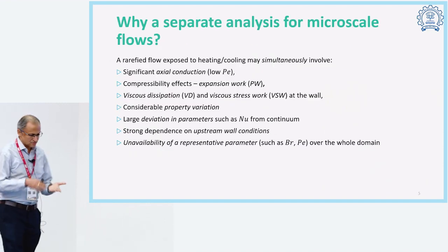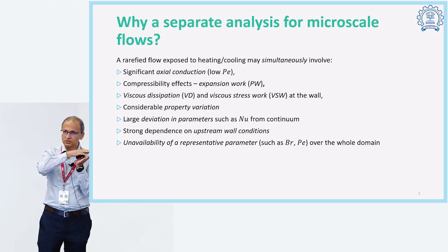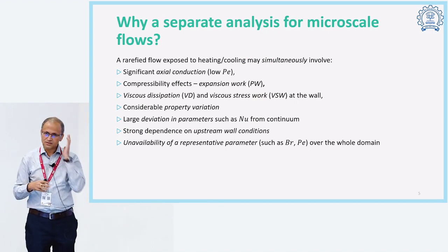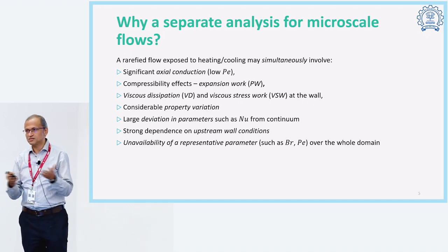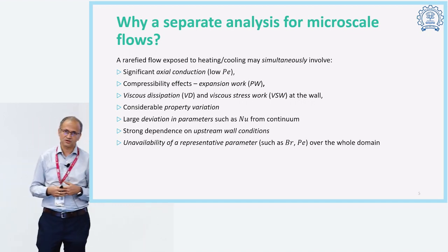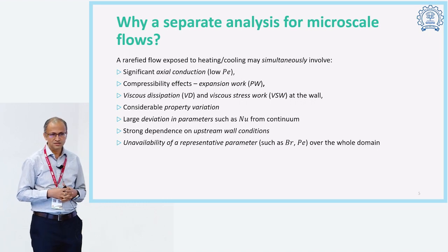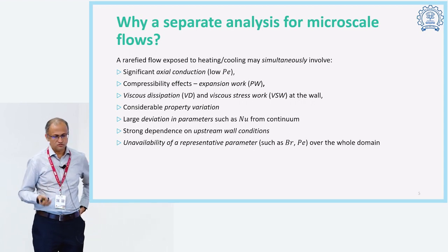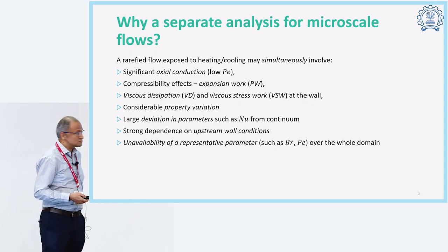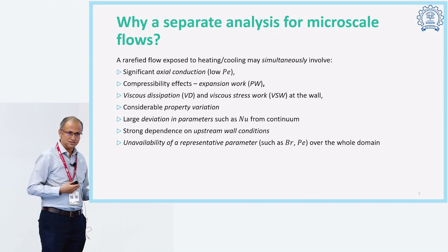Now, I will take a very simple flow in a channel sort of a situation and look at the heat transfer. When we look at the heat transfer of that, one can say, okay, this is a classical problem. People have solved it. The textbooks have it. The solution of that, we know the Nusselt number will be 4.36, 3.65, depending on what sort of a boundary condition you put. But so what is new, what is different, and why is the difference?